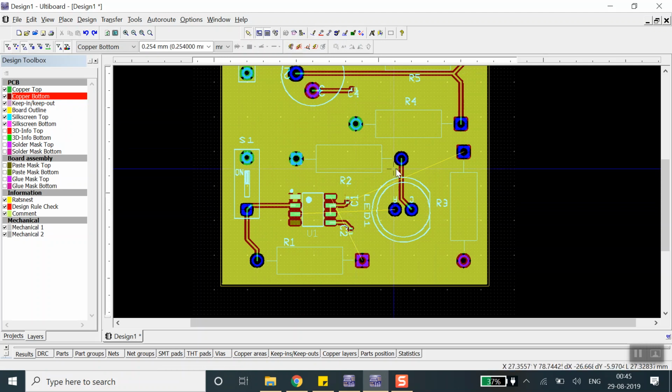Okay, I will show you this connection over here. Now you will see that when I am touching the ground plane, the board line is getting selected, and I don't want that to happen. So I will just unselect this one and that will be all right. And I want to select the traces now, so I will enable selecting the traces.